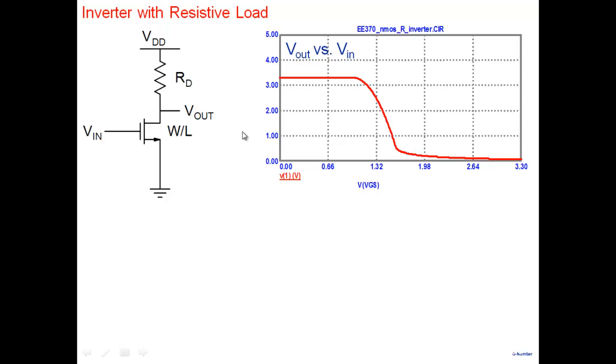Now, when we design an inverter, what are the important characteristics we should look for? The first thing, of course, is it should act as an inverter. That is what we call the functionality. It should obey the functionality. The other one is that we've already seen that area is important. How much area my inverter takes has a bearing on how much area my NAND gate would take, and similarly flip-flops, registers, adders, and all of that. They are all related to the area of a basic unit cell, which is an inverter. And so area is important for us.